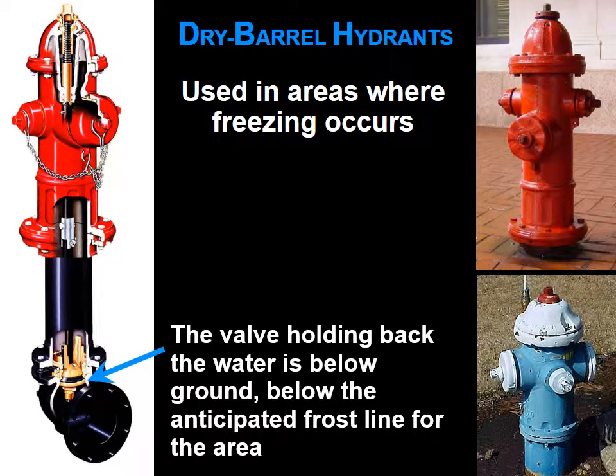Also here, when you open a hydrant, make sure you fully open it. Make sure you turn it all the way on, and when you turn it off, make sure you turn it all the way off. This little thing that the arrow is pointing to on the bottom has a drain in it, and that's what lets all the water drain out when you shut the hydrant off, and it drains out into the ground.